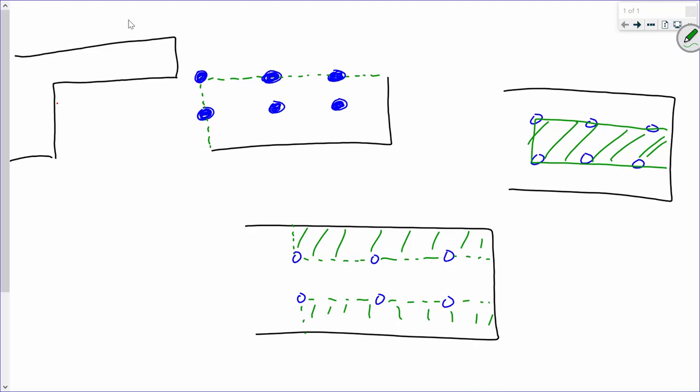If I had to look at these 3 failure paths, if I had to guess which one is most likely to govern based on these conceptual images, I'm going to say it's the one on the top left, okay? And the reason why I am saying that is because this one rips through the smallest amount of area, okay? You want a conceptual understanding of that? Let's go back to my corkboard image, okay?